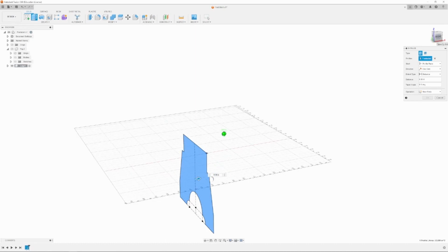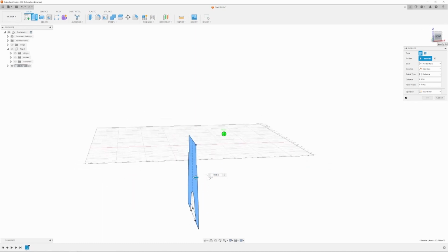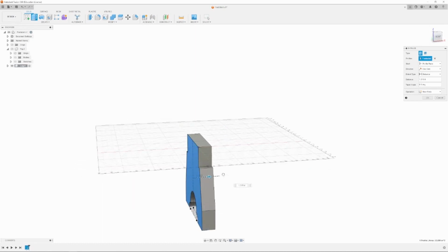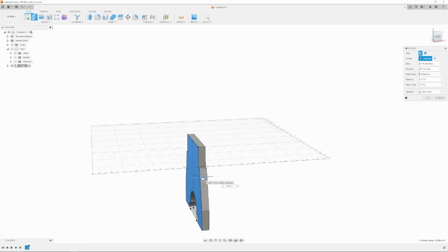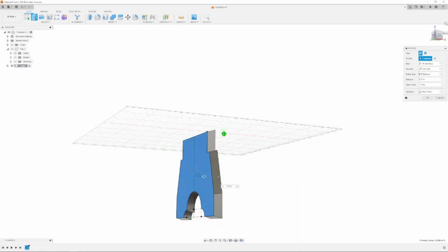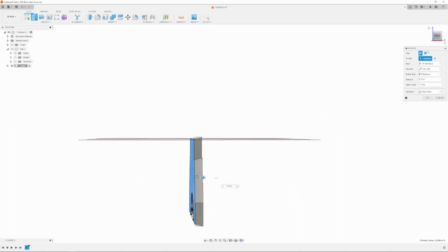But when we slant this over, it's not just going to be extruded like this, it's actually going to be brought up at an angle. And so we're going to extrude it at an angle instead. So I can bring it this way, 0.75, and in the options up here I can actually specify a taper angle. And I don't think this is actually going to do what we want because it's tapering in all directions. So I kind of forgot that.